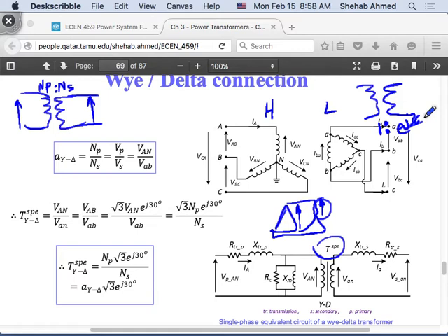The actual turns ratio is not numbers anymore. It's numbers and an angle, right? So this numbers and an angle depends on what this T, this new turns ratio, is. This is the actual circuit before converting to per unit, right? So the T, the new turns ratio in a star delta transformer, is the turns ratio between what?